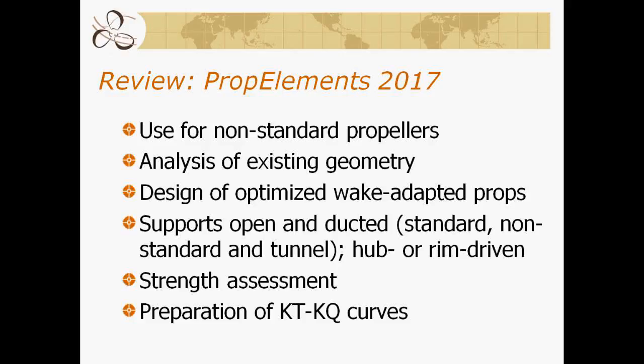So just as a review, PropElements 2017 is a tool used for non-standard propellers. Series propellers, a true B series, a true Gawn, are well represented by the statistical empirical methods. It allows for analysis of existing geometry, but we can also do design of optimized wake-adapted propellers. It supports open and ducted propulsors with standard nozzles, non-standard, and even tunnels, hub-driven or rim-driven. It gives you a strength assessment and a preparation of the KT-KQ curves.